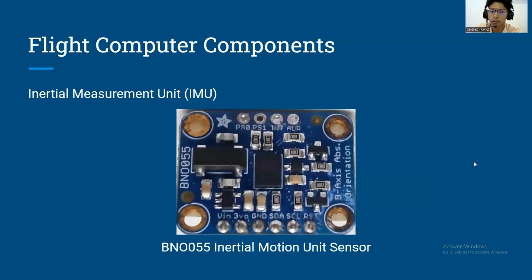We are able to demonstrate the orientation of the system at any specific time using a BNO 055 inertial measurement unit sensor. This reads gravity, accelerometer, magnetometer, and gyroscope. Using a Kalman filter, we are able to measure a smooth acceleration, angular velocity, and 3D orientation of the object.